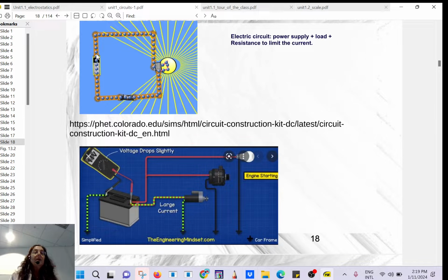So here you have plus, deliver the energy, go back. Do you see a closed circuit here? So how do they come back to base? What is it that you are using here? So no, it's DC, but you need a way to return to base, right? You need a return path. And instead of using a wire to return to base, they use the chassis of the car. The chassis of the car is made of metal, and that will be your return path.